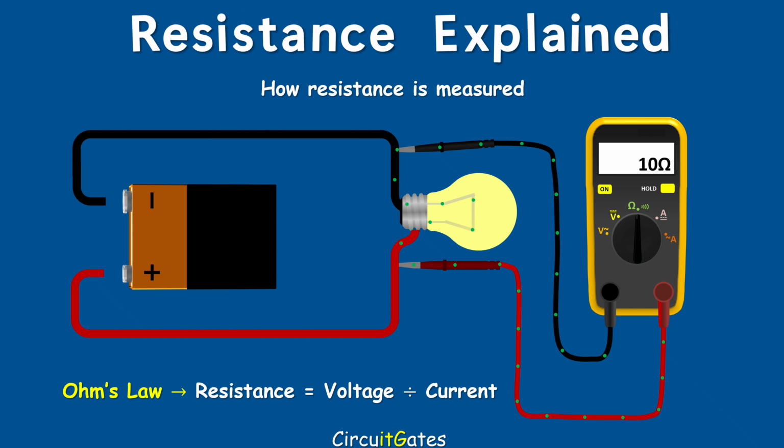The reason for disconnecting the component being measured is that the ohmmeter has its own battery used to supply voltage and current to the component being measured. If we don't disconnect the component being measured, or switch off the component's power supply, the component's power supply will damage the ohmmeter and its battery, or the ohmmeter may give false results.